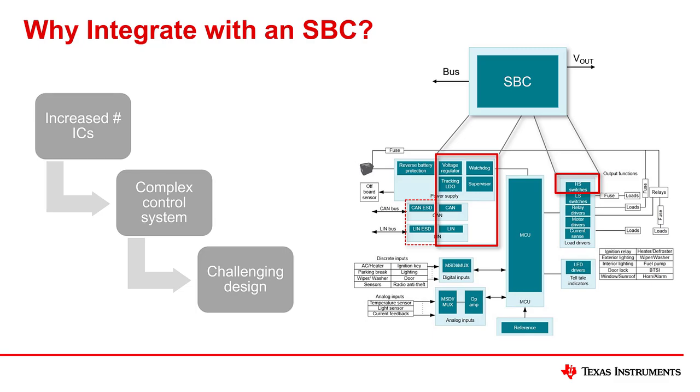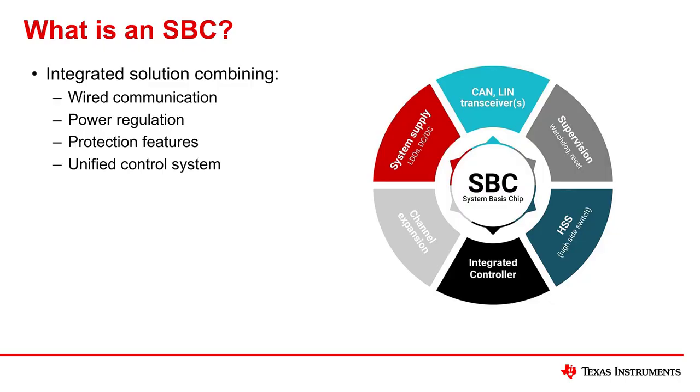As you can see, we have an example showing that the SBC could be used to replace a discrete voltage regulator, high-side switches, and transceivers, simplifying overall design. Integrated solutions reduce the number of ICs required to support every design function. An integrated SBC solution can simplify and scale an overall design or application.